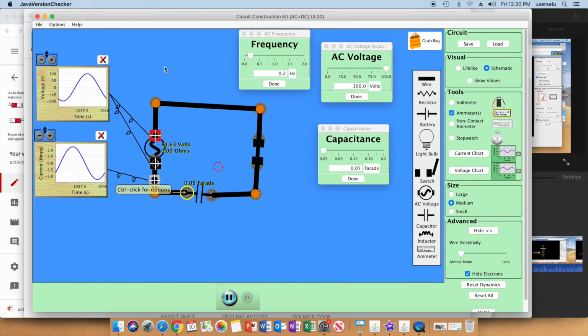First of all, I want to point out, it's weird simply because there is a flowing current. Now notice, the current is on this bottom scale. It's varying between about +7 and -7, roughly. And that's +7 amps to -7 amps as the voltage goes from +100 to -100. One of the first things to note, though, is that the current does constantly flow. If you want a little bit of a discussion about that, maybe you can refer to the slides. This capacitor is charging and discharging constantly during the alternating current.